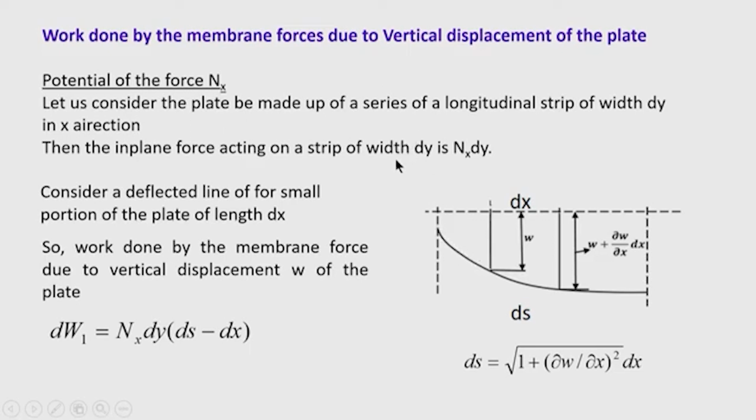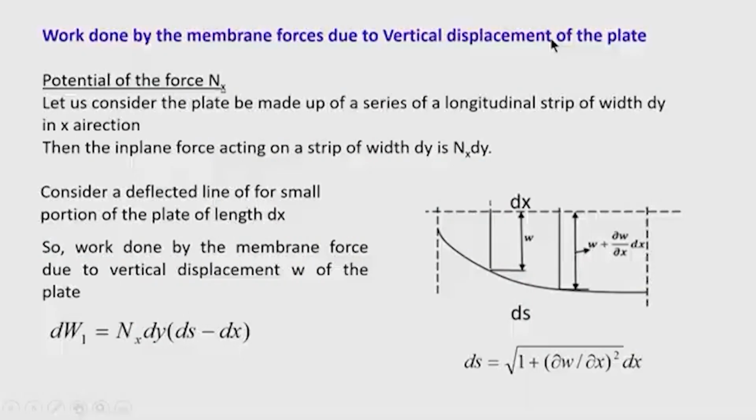So, consider a rectangular plate. In the x direction we take a strip of width dy. In this strip, if Nx is the force along the x direction, then Nx dy is the force on the strip in the x direction. Now, consider the deflected surface in the x direction.